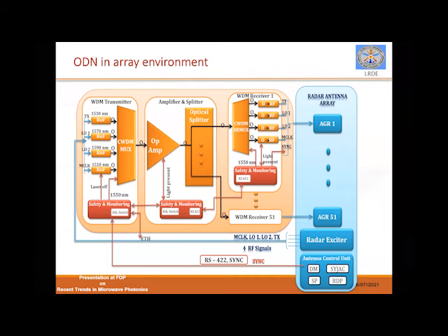So each of the signals is assigned a different wavelength, and then multiplexed by using the CWDM mux, and it is passed through an optical amplifier. Conventionally nowadays, after 1990 onwards, erbium doped fiber amplifiers can be used for the amplification of signals in the 1550 range. So this output is split and passed through a demux, and to obtain the original signal we are using an RF receiver.